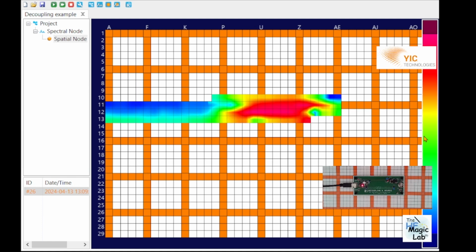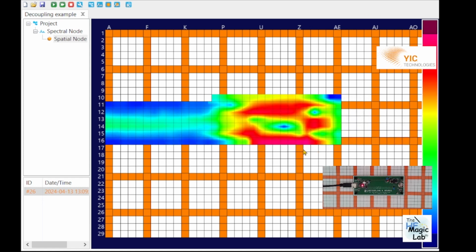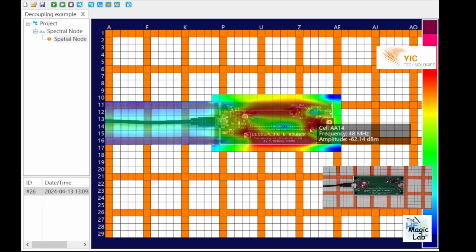We can start to identify how in my PCB I have a loop. This is the loop we were explaining at the beginning of the video. No? So the energy is taking basically the current, the high frequency current is taking the full area of the PCB. And that was the problem created in power integrity, and that was solved by the decoupling capacitor. If we activate the overlay, we can see how this current path match with the position of the components.